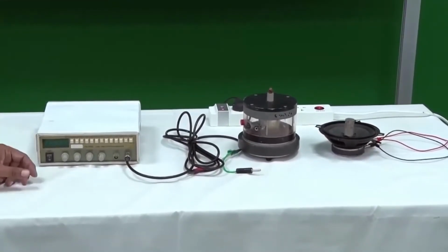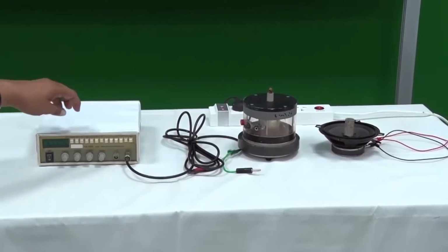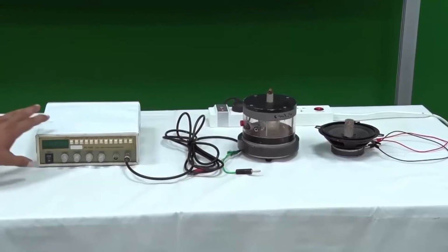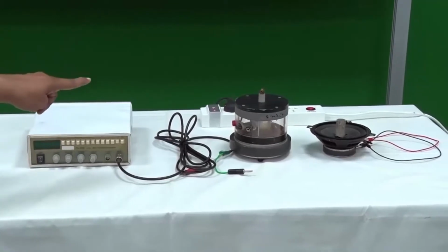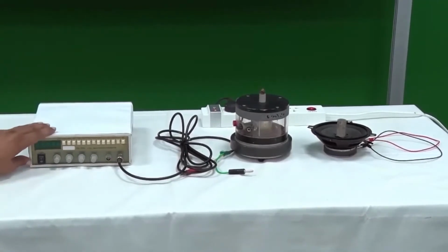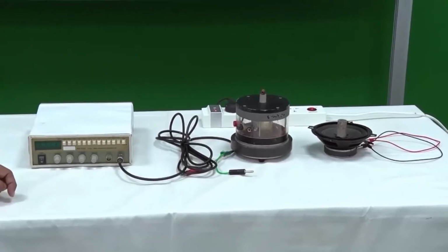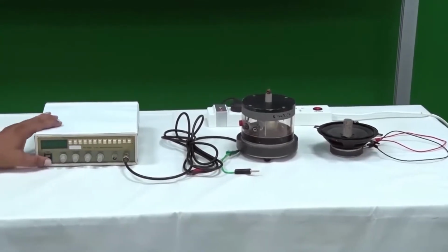So, we need DC voltages, but still we are using the 220 volt and 50 hertz power, because we do all our DC conversions in this unit itself, otherwise we will have to carry batteries. So, it operates on AC, but it is not using that AC, because that AC is 50 hertz only, and it is producing its own AC at a very different frequency, derived from the DC voltages which are converted from that power supply, and then that DC is actually used for this oscillator circuit.